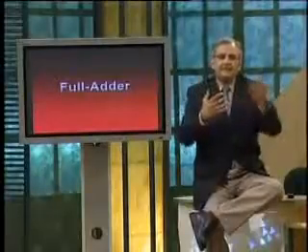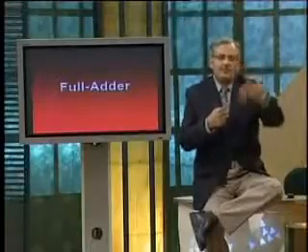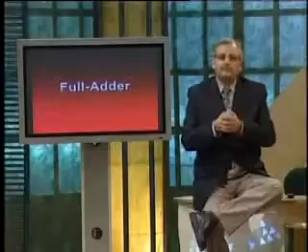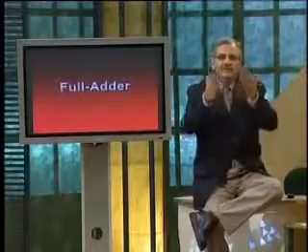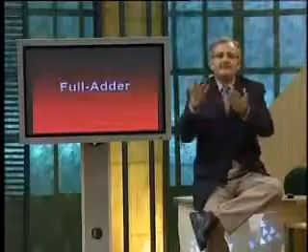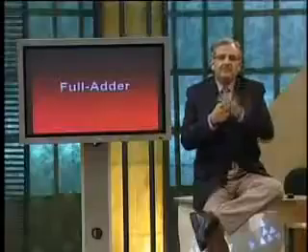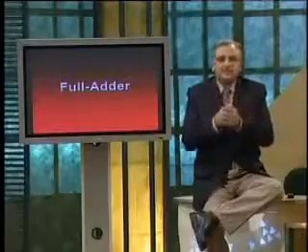Therefore, three columns representing the variables A, B, and C in. So there are 8 possible input combinations. Now let us have a look at the 8 input combinations, and let's determine the sum output and the carry out output. Now for a combination 0, 0, 0, the sum output has to be a 0.